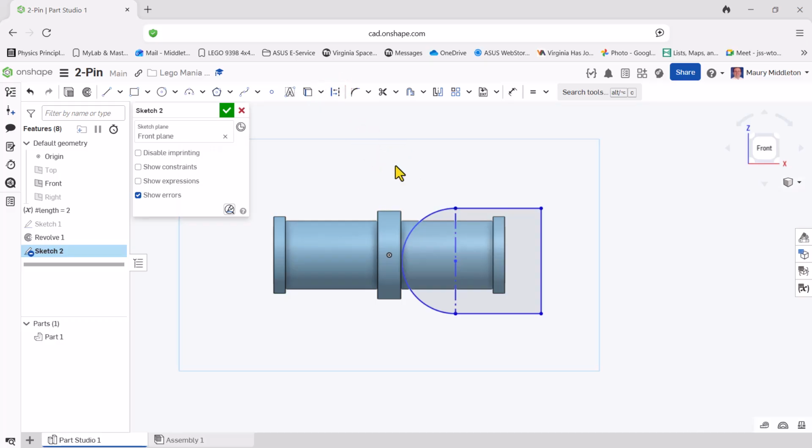Now what I'd like to do is to close this down in size. So I'm going to go ahead and select a dimension on this. And let me go ahead and align it to the center, to the origin first. And I'm going to do that by drawing a line from the origin to the center point. And I'm going to make that a construction line too as well.